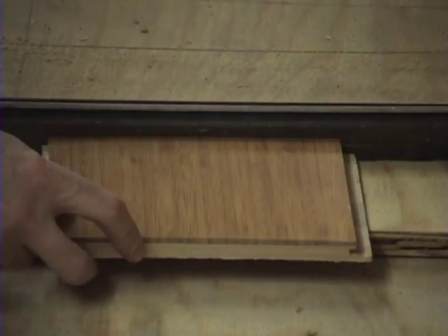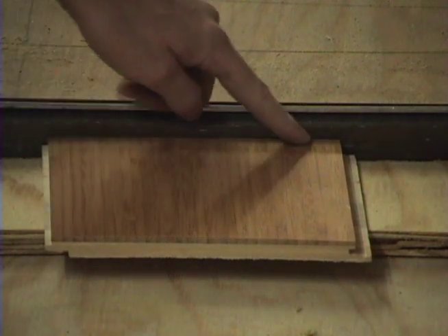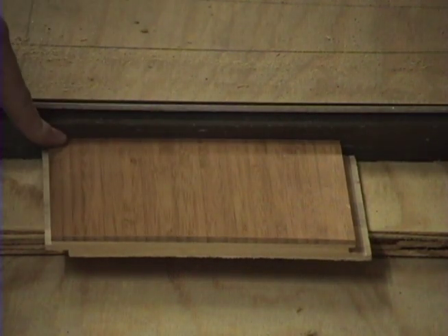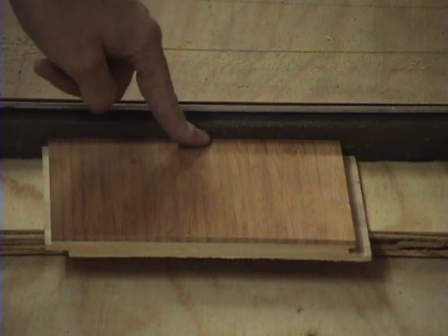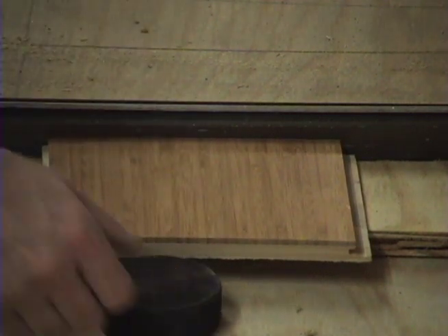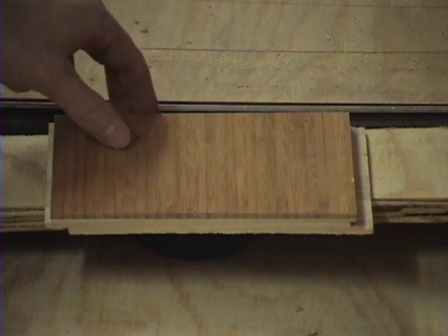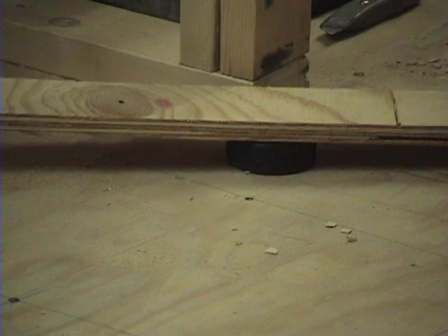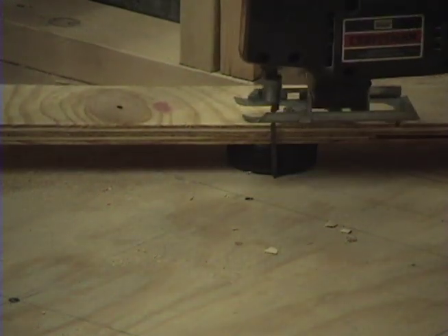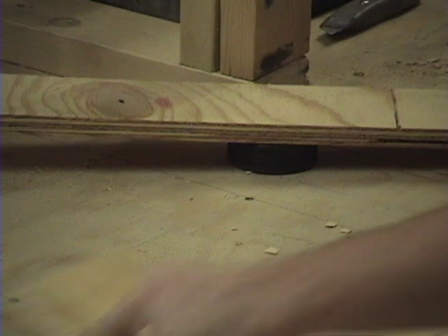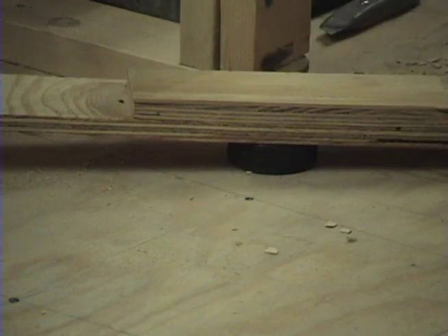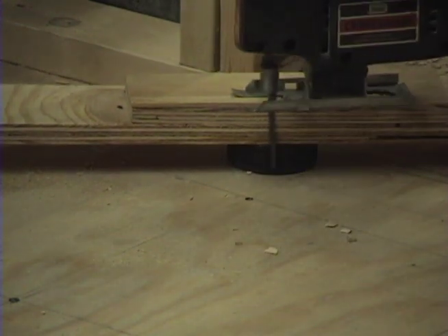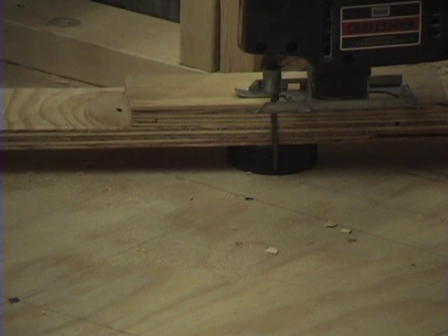In order to make the threshold of the door flush with the floor, I needed to look at my construction and found that if I cut my subfloor and recessed the door, it would be perfect when I finished the floor with the bamboo flooring I had selected. This means that I need to cut the subfloor, place a few more hockey pucks for the door to rest on, and seal the whole construction. We made the cut in the floor with a circular saw to start, and then finished it with a jigsaw. The jigsaw blade is longer than the depth of the floor and the puck, so I used another piece of subfloor to lift the jigsaw up so it would clear the concrete below.